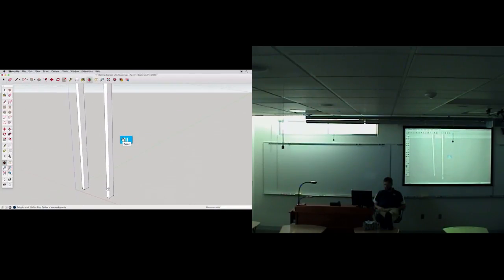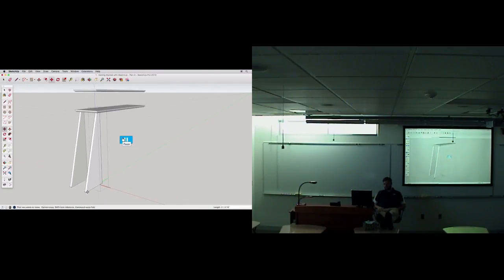Make sure you are editing the leg component, then select this lower outside edge and start moving it with the Move tool. The copied leg component is reflecting the same changes, and this is what makes a component very powerful. Any changes you make to one component are also made to any of the same components in the model.